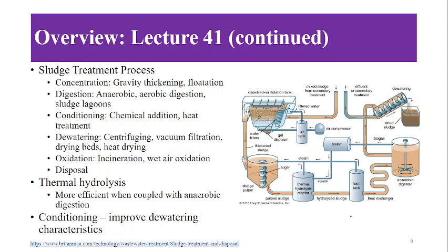Next is digestion. Here, the organic content which is there, the biodegradable content, is acted upon by microbes, whether in the presence of oxygen or absence of oxygen, and because of that this organic content is degraded into simpler molecules.